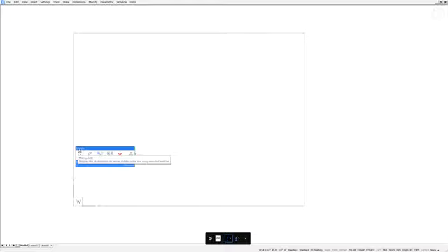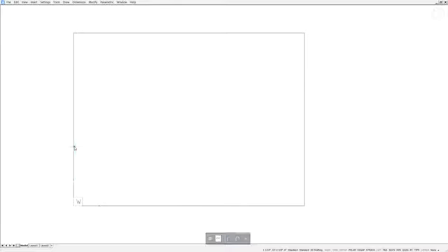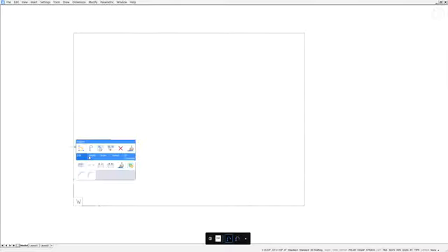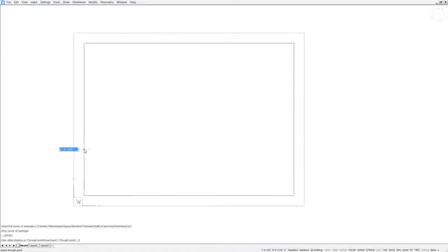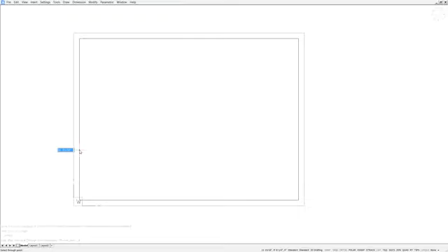If that's still not what I want, I can even go further and expand it more, where I can get these modify tools and edit tools. For example, edit is specifically relevant to polyline type objects. So I can very easily access a variety of commands. This makes it super easy for me to work in BricsCAD without having to worry about where my UI elements are. They're right there at the quad.